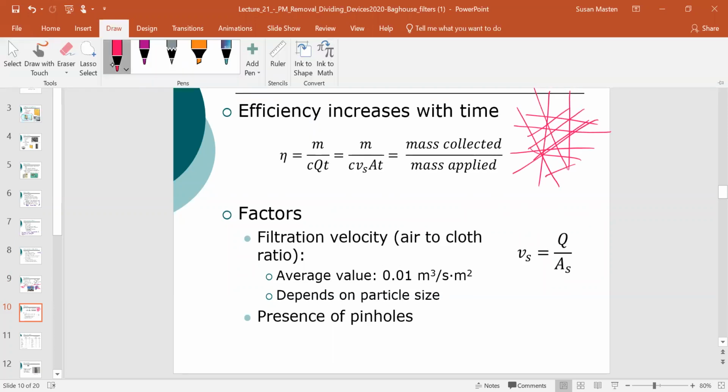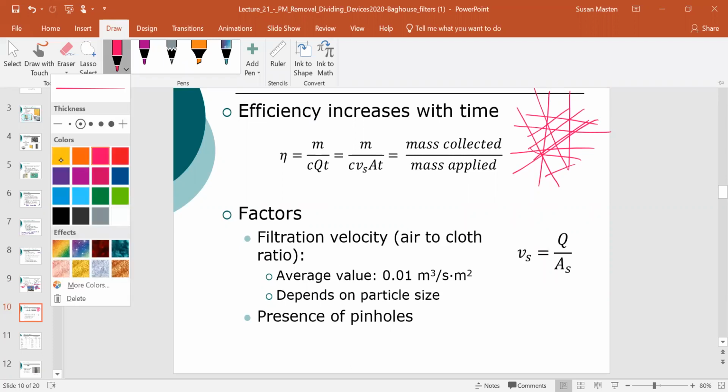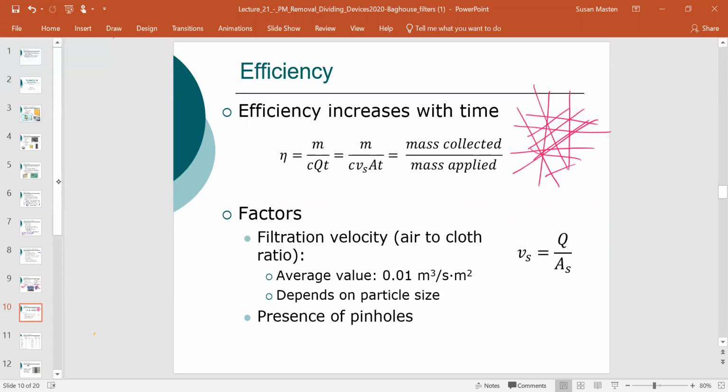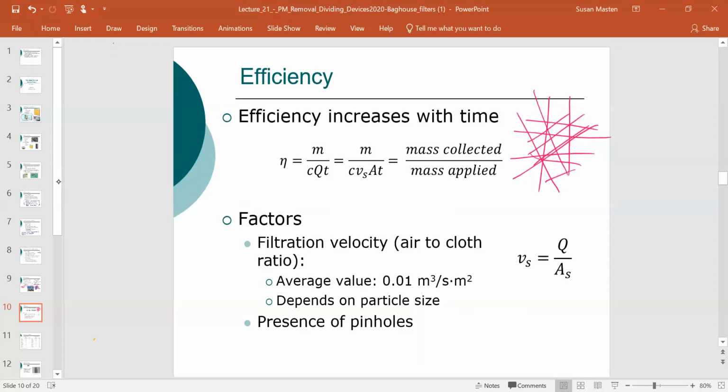We've got these particles that are getting stuck in the filter, and some are really large and they stick on the outside. You can think of it almost as a coating. So over time, you're going to get particles sticking. They decrease the pore space, so you see a decrease in pore space, and you see what's referred to as a filter cake.